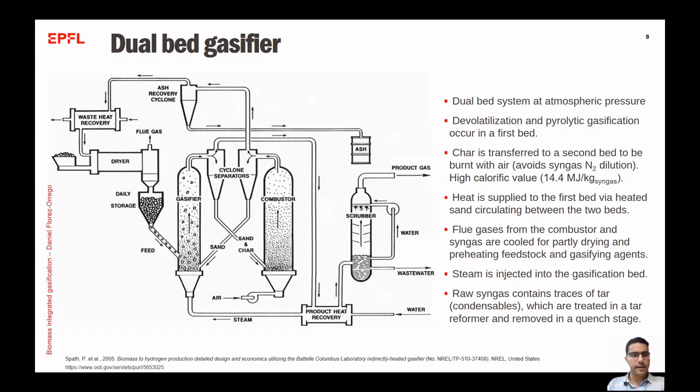The biomass is sent to a silo, a storage system that feeds the reduction column, in which the biomass is gasified by bubbling it using steam as gasifying agent. The syngas is then removed from the top, separating the particles that go into a sand and char combustion, and then this syngas is sent to the waste heat recovery, and then the scrubber for obtaining a produced gas.